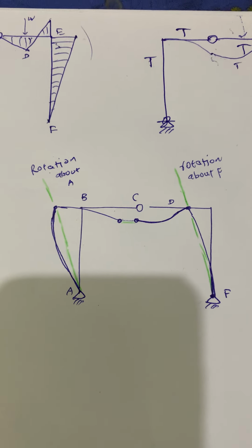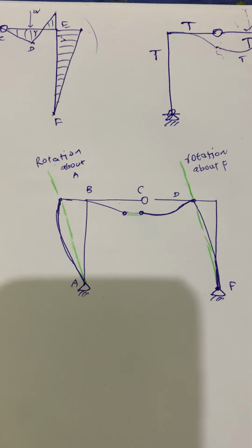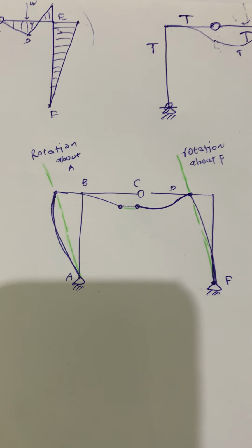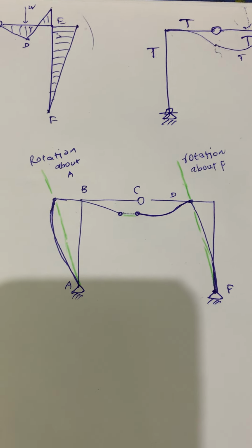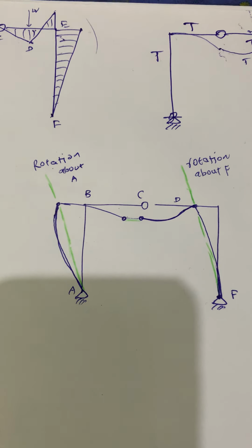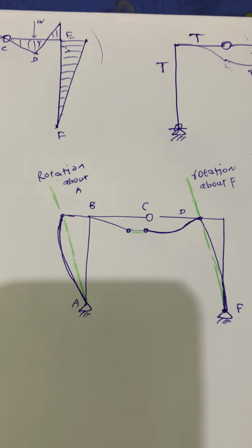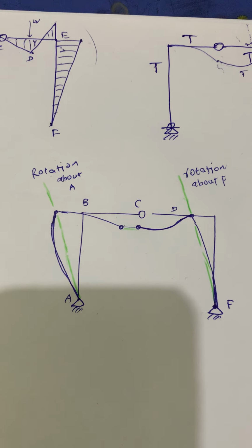However, our frame is of course in reality continuous, and the two points C have to be coincident since they are shared by both the left and right parts of the frame. This can be achieved if we allow the points B and E to move horizontally.